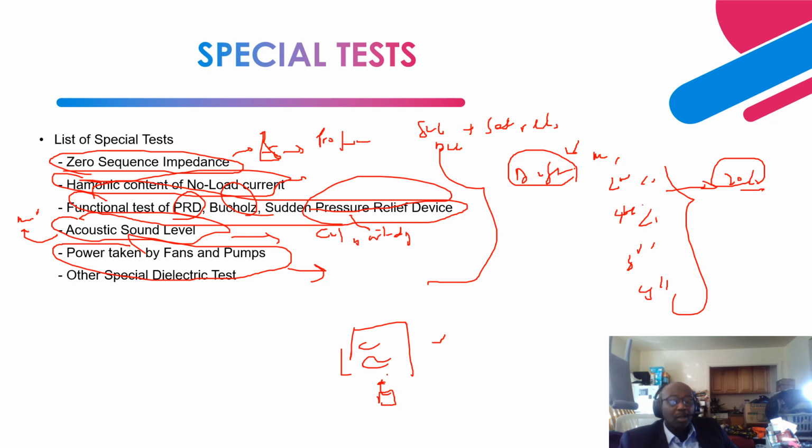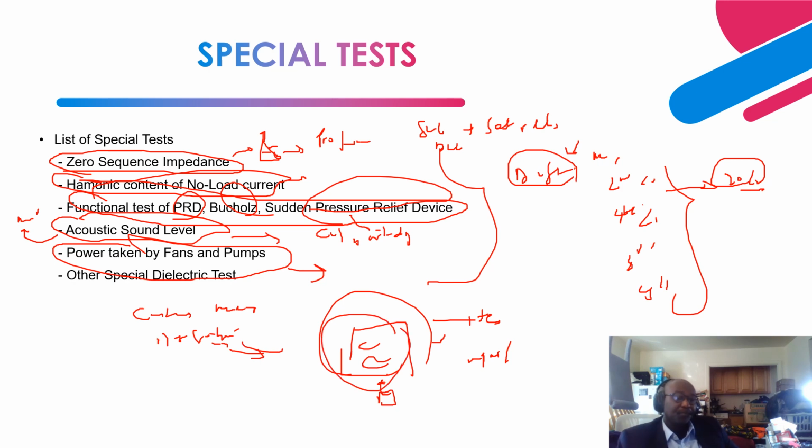After the testing, the manufacturer is going to provide the testing results, the amount of power that is going to be taken by these auxiliary devices, so that, based on that, their customer can determine the size of the MCC bucket, the power that it needs to provide from the MCC switchgear for these auxiliary devices.